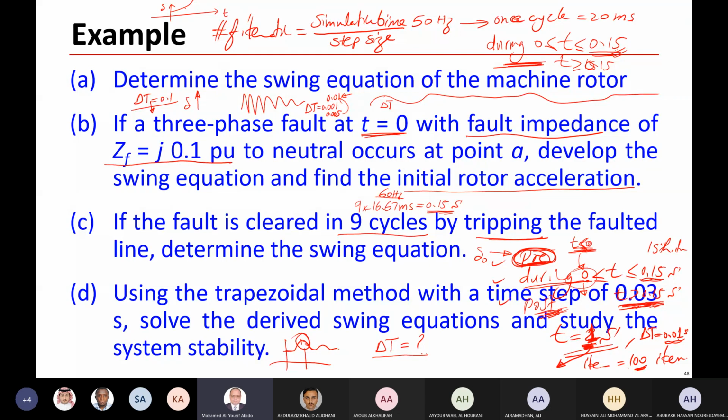And then if it starts decreasing, then the controller will respond at that time. So the damping of the other controllers will be active, and this will help in reducing it more and more. The problem is that this is the first swing, and if the system in the first swing is unstable, the system goes as such. Okay? Is it clear?